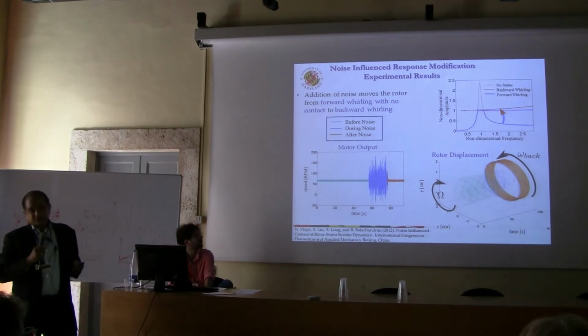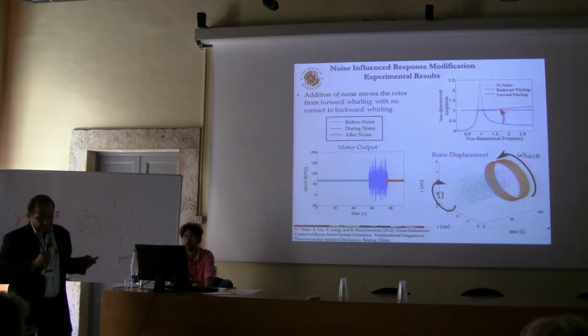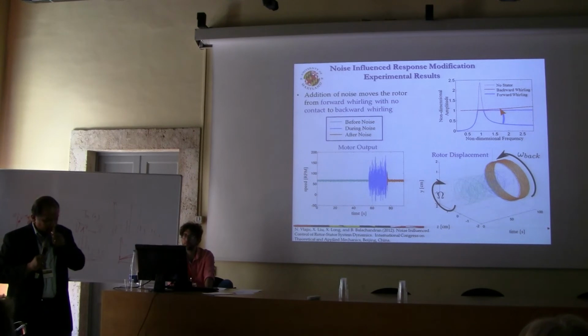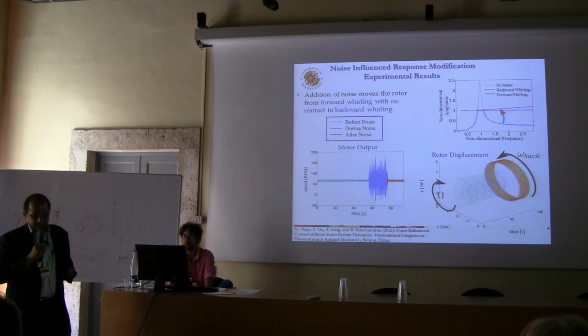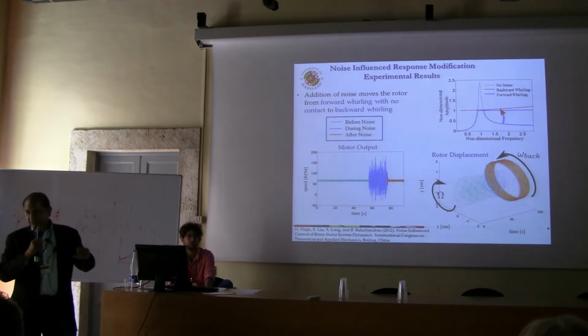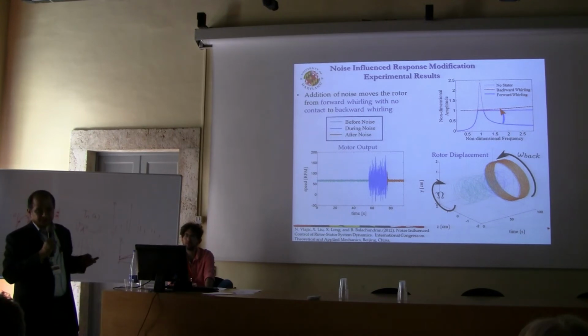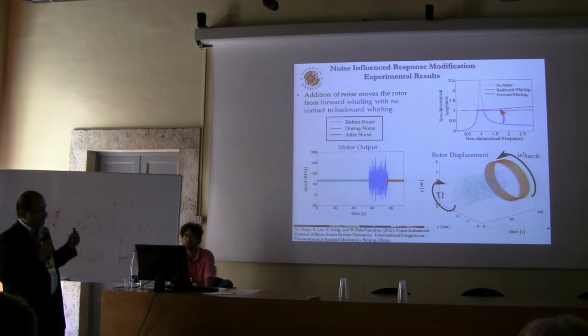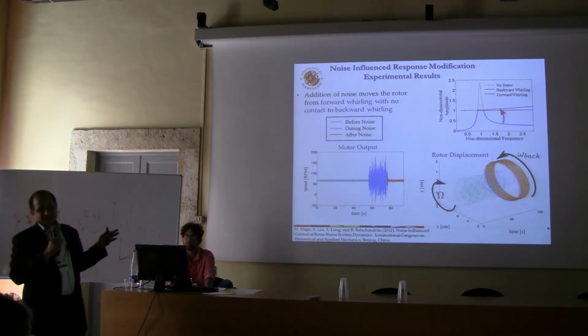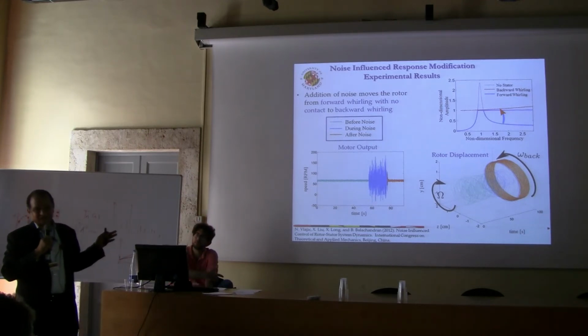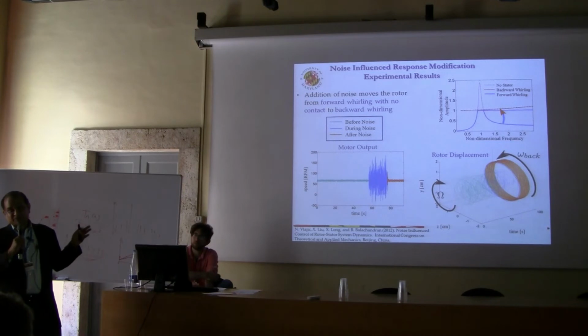Okay, so this is noise assisted steering. So this is something that can be done. I think most drill string operations these days have a secondary motor which is not on the top but somewhere further down the drill string itself, which could be used to facilitate secondary frequency inputs into the system itself. Although this is not something you like to do in practice. You're basically going from a state where the amplitude is low to a case where the whirling mode is fairly large. Right?